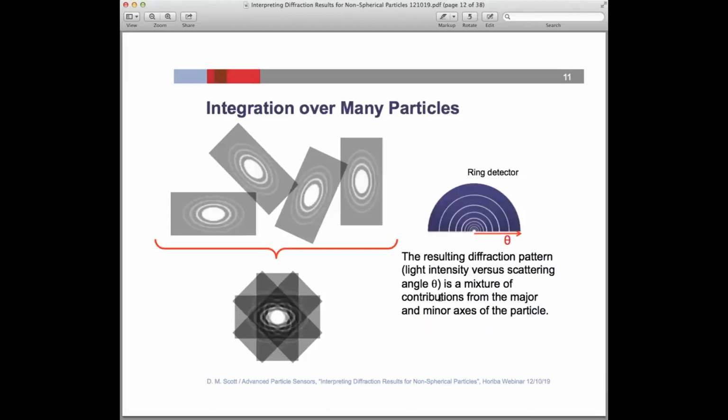When we're dealing with multiple particles, and even if we're dealing with one particle, you might end up sampling that one particle's laser diffraction pattern many times during the transit of the particle through the instrument, and as it recirculates, you'll pick it up. But typically, you have thousands or hundreds of thousands or millions of particles, depending upon the particle size, flowing through the instrument.